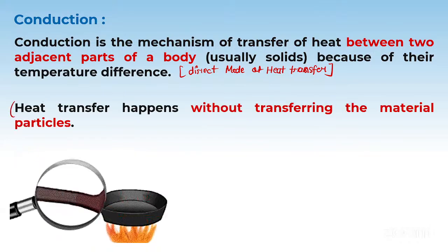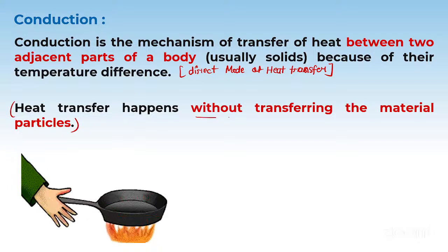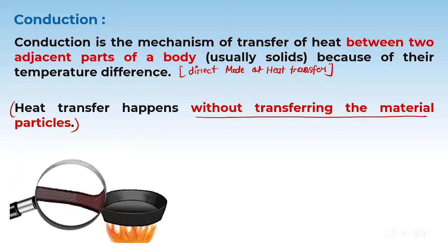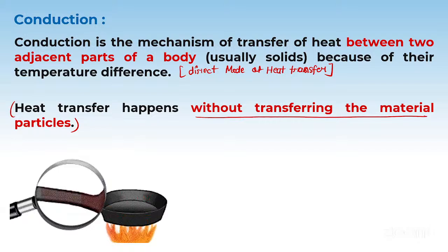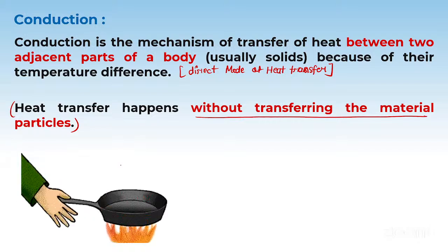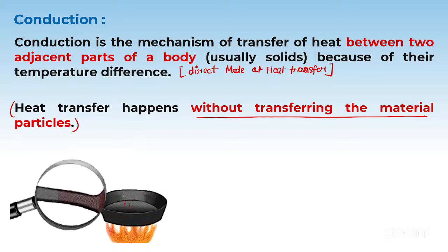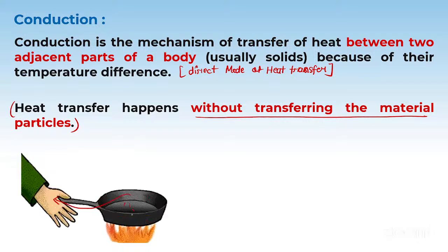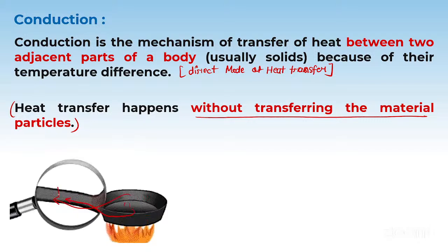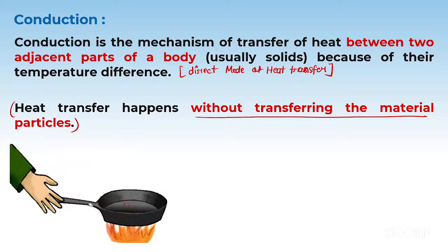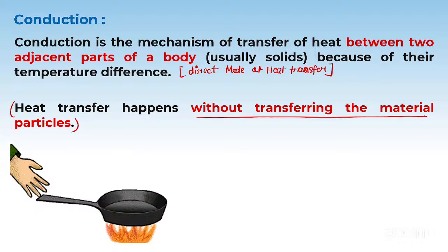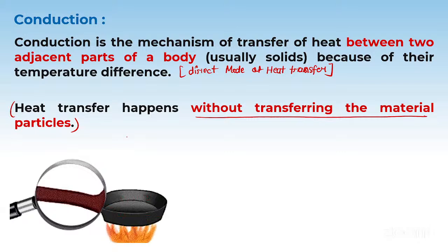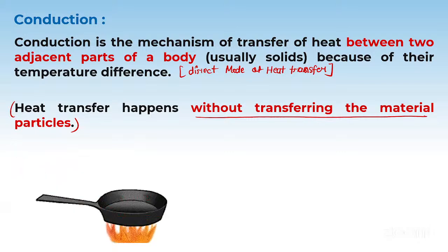But the one point to remember here, you can underline it, is that heat transfer in conduction happens without transferring the material of the part. ठीक है, मतलब क्या होगा इसका कि if you raise the temperature of this pan, ऐसा तो नहीं है कि पैन की ये मेटल यहाँ पे आ जाएगी, ये मेटल फ्लो करेगा यहाँ पे इस एंड का टेम्परेचर रेज करने के लिए, नहीं ना. So when the material is not required to flow from one point to another point to transfer the heat, that mode is also termed as conduction. ठीक है, so without transferring the material particles, it happens.